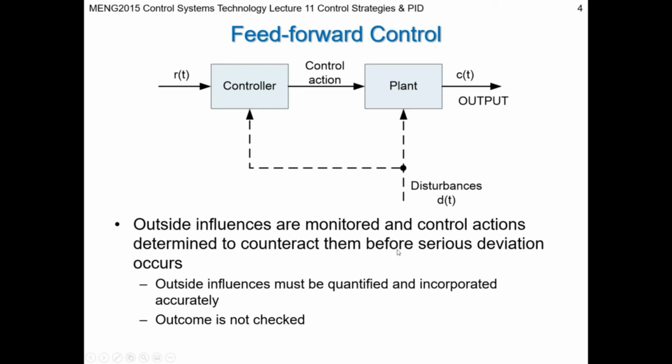So in a pure feed-forward control system, this is one configuration where you're measuring disturbances and correcting for them preemptively, but you could also be measuring your reference input, your set point. And if there are changes in your input, you could also preemptively act on those before you're detecting that error differential between the input and the feedback. Or you could have a preemptive adjustment of some control parameter based on your reference before your output starts to vary from the set point condition.